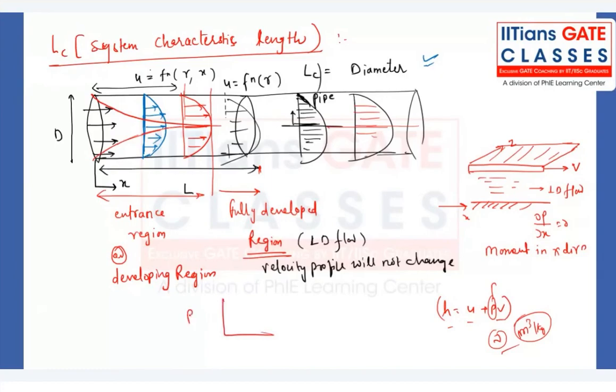Suppose on a PV diagram you have a constant pressure process 1 to 2 and a constant temperature process 1 to 3. Work done will be different, it will not be the same. You cannot say work equals the value at a point, and it is not a point function. That's why we cannot say dW, we say delta W. That is the meaning of point function and path function.